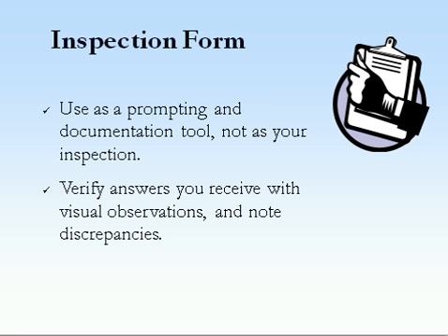Make sure that you've got their production operating hours, cleanup periods, any seasonal variations or scheduled shutdowns. Have there been any facility changes that they forgot to tell you about, or are they anticipating any changes in the near future? Water usage, wastewater generated: you want to look into where they get their water.